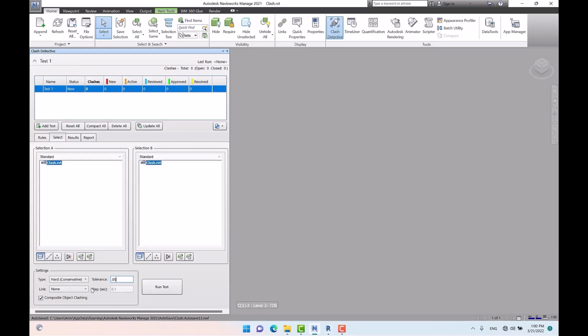And here if I specify 0.05, it is the minimum value for two objects overlapping each other. For example, we got two objects that are exactly parallel and overlap each other slightly at their ends. And here if I specify 5 centimeters, the 5 centimeters overlapping is not going to be reported, since we are not going to face problems.